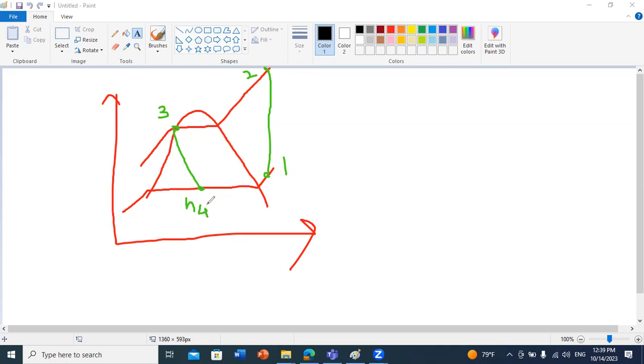All we have to do, we know H4, H4 equals H3. And we are entering the evaporator and we'll have change of phase here. The change of phase will continue until reaching point 1, and the cycle will repeat. So we need to determine the quality at this point, if we want to calculate other properties than H, such as the internal energy or the entropy.